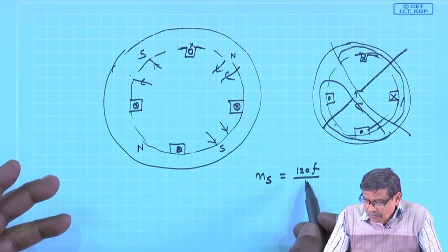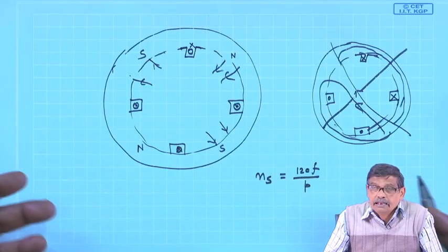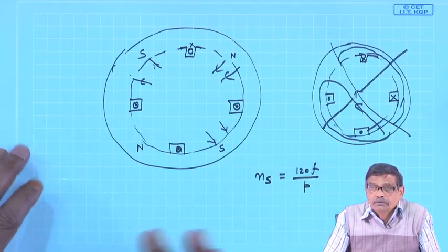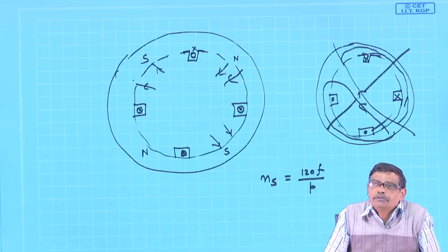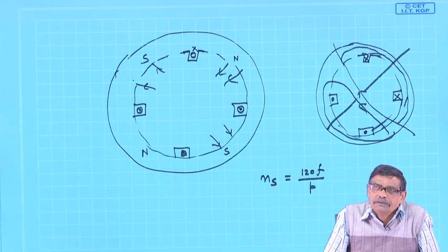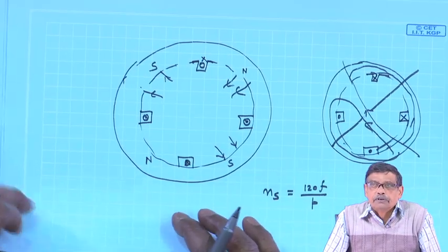So, people thought whether with the same windings p can be changed, hence Ns, and this cannot be done continuously. No continuous speed control is possible, only 2 discrete levels of speed you can have from the same induction motor. Anyway, we will continue our discussion from this point. Thank you.